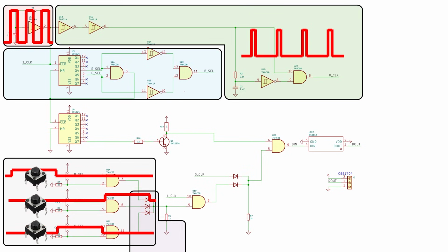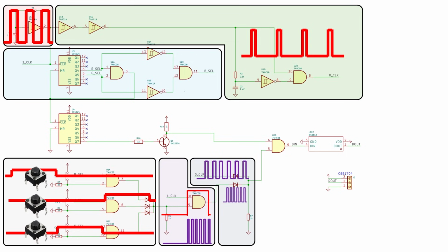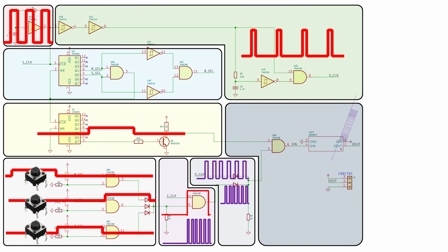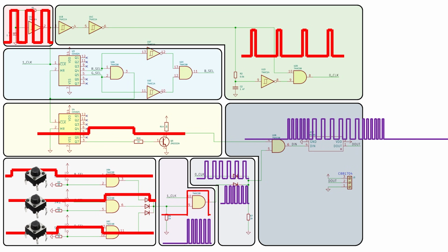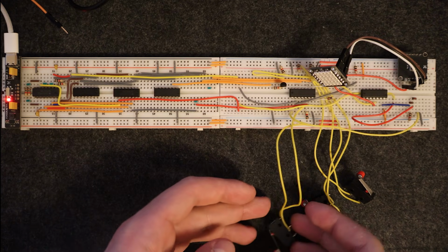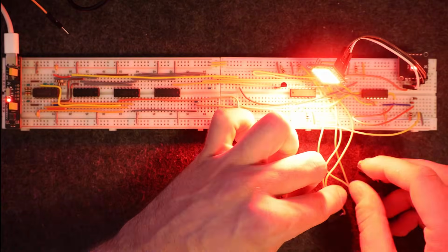We turn those identification signal envelopes into logic 1 pulses. Then we build logic to decide whether a long pulse or a short pulse should be sent. Last but not least, we generate a reset signal and combine everything in the final stage to create an addressable LED data stream. Here's the first test after building it on a 5x5 LED matrix. When nothing is pressed, the lights are off. Using the buttons, I can switch on green, red, blue, or mix red and blue to get purple.